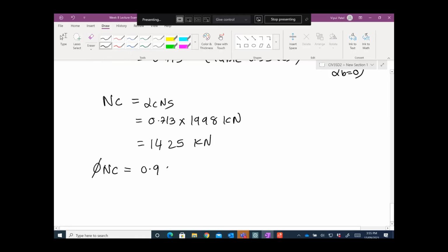And if you just want to calculate with the reduction factors, there is another 10% penalty, saying that you will be reduced because of uncertainty. You might forget to apply something, and boundary conditions in the real world, you will not have pin columns. There might be some kind of uncertainties that apply there. So that's the quick overview on that one.